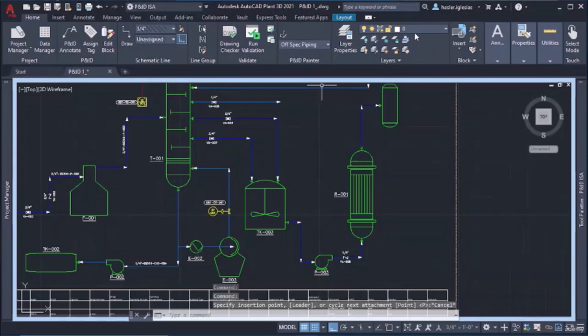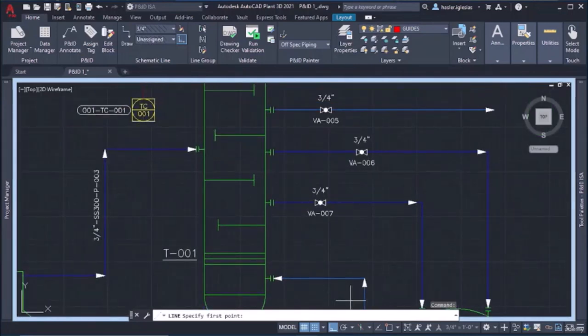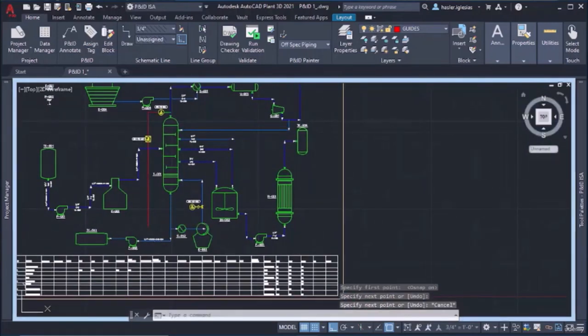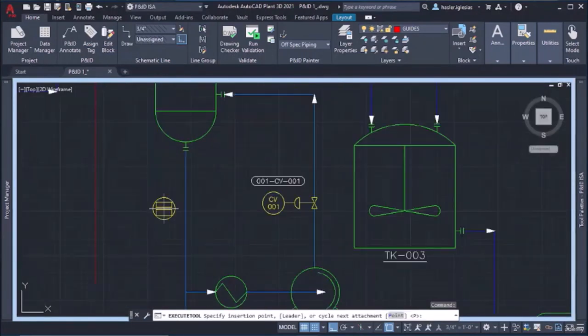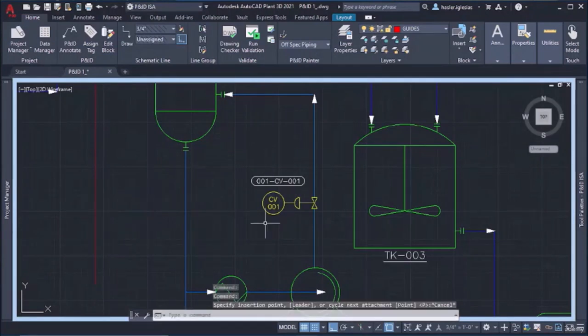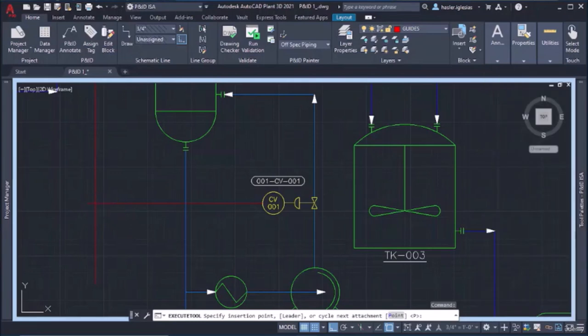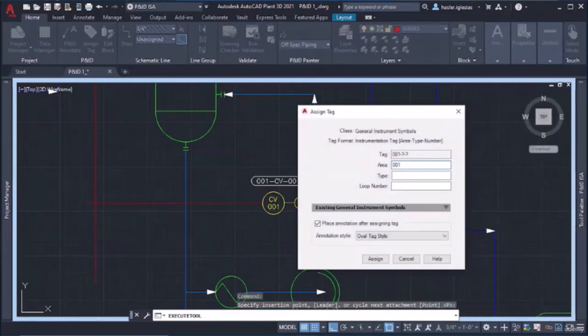For that, I'm going to draw a guideline. Remember the guidelines, okay? I'm going to draw a line. It's going to be from the middle. Let's activate snap from the middle downwards, okay? And now I can place this one. Well, I must draw another line. Okay, so in that corner, I'm going to place the instrument. It's going to be, let's say, field discrete, primarily accessible. Let's put this one. Okay, so it's area 1.